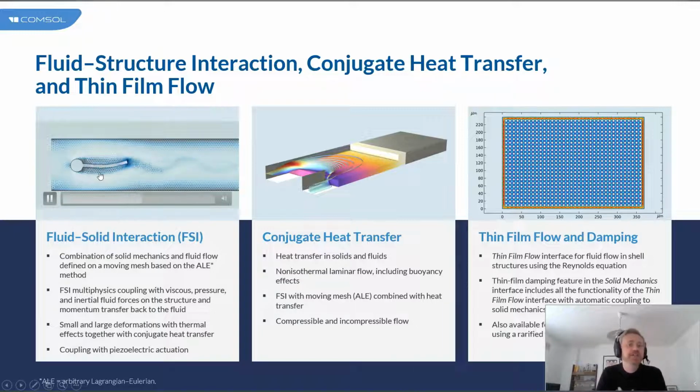the left-hand side is fluid structure interaction, where we're looking at combining fluid flow with mechanics. And what you can see in this animation is a scenario where we have a fluid which is deforming a structure. And that's one way that we can model fluid structure interaction. So the flow deforms the structure. The alternative way would be to look at the mechanical deformation driving the flow, which might be something that we would look at if we were modeling a pump, for example.